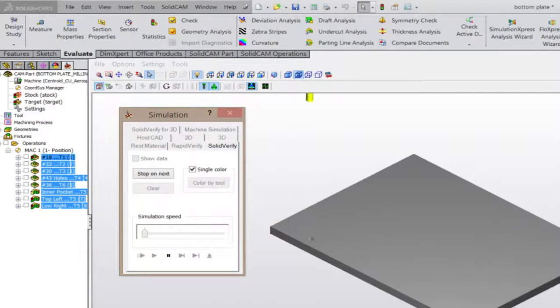Notice we can see the pecs now. What did they have to select to get those pecs? It was that step down feature. So they wanted to see the pecs, so they selected that step down. If you don't select it, it'll just go straight through. Why do you suppose they give you the option of seeing those pecs? Right. If you have 500 holes with 20 pecs each, you don't want to sit there and watch that thing all day long. All right. So they pecked it.